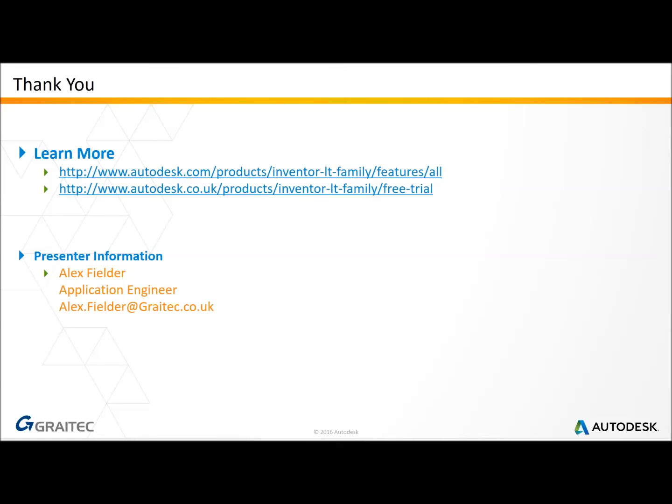So what did we cover today? We talked about DWG Underlay and the ability to reuse 2D legacy AutoCAD data. We've talked about importing of existing 3D CAD data, so whether it be step files or, as my example there, a solid part file. We've touched on Freeform functionality, and lastly we've talked a little bit in depth there about taking a design, updating it, and seeing the drawing go from what it was to what it was updated to.